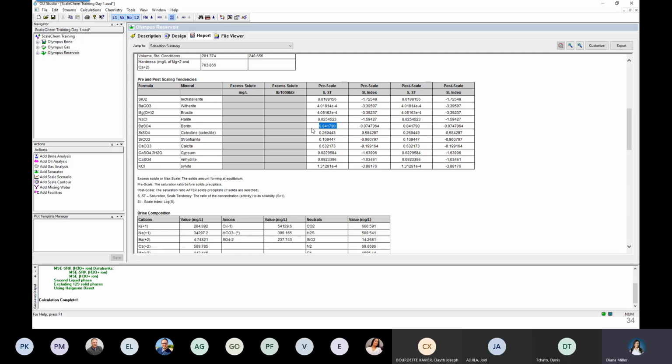So with these initial results, what it means is that it's possible that barite or calcite would be at equilibrium in the reservoir. And this is because the measured values were brought down to reservoir conditions and are close to saturation. Is there any question?